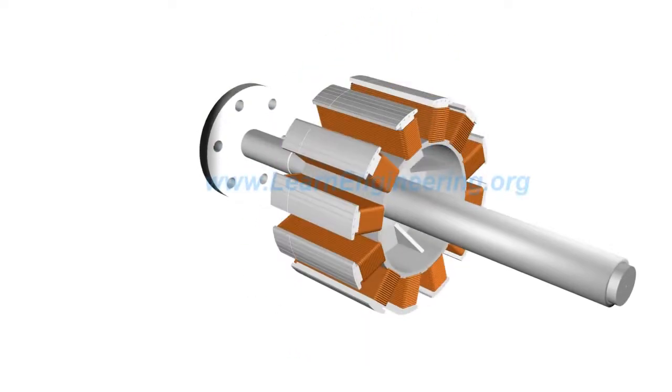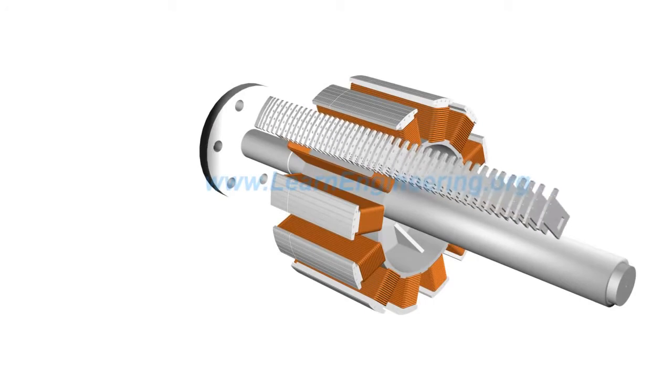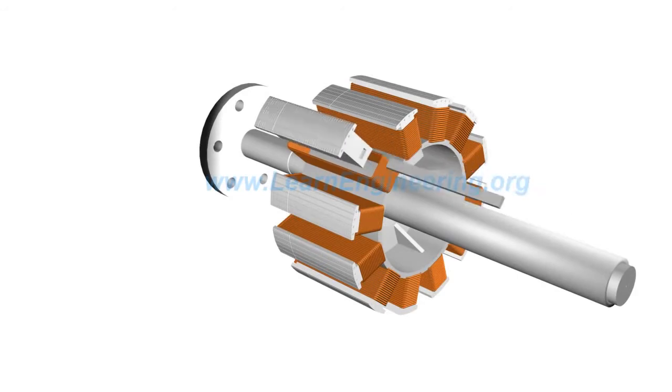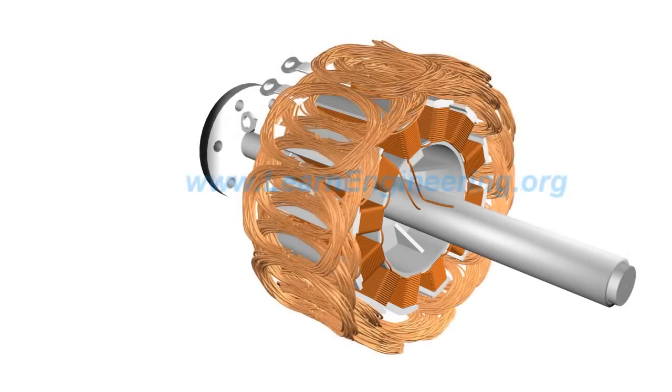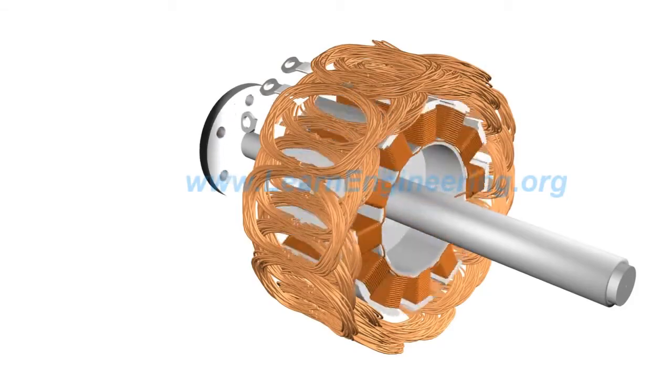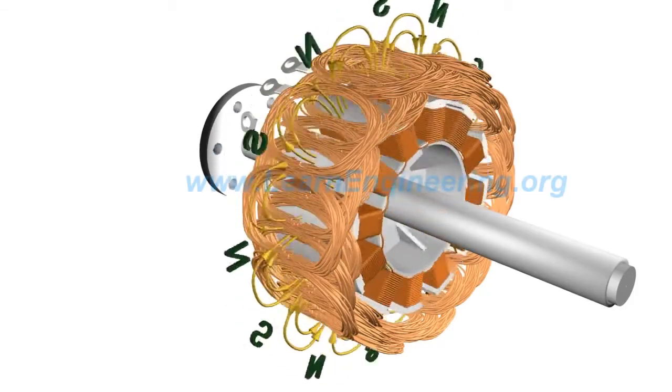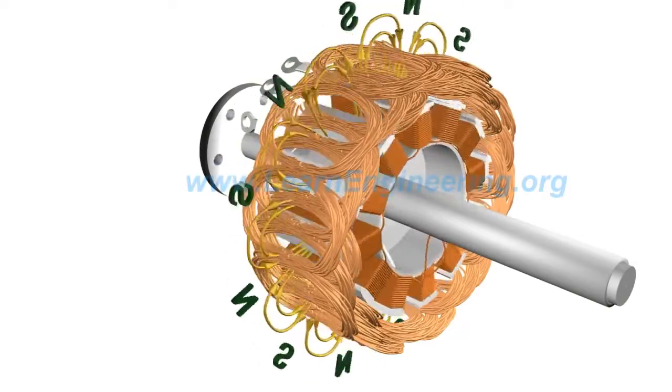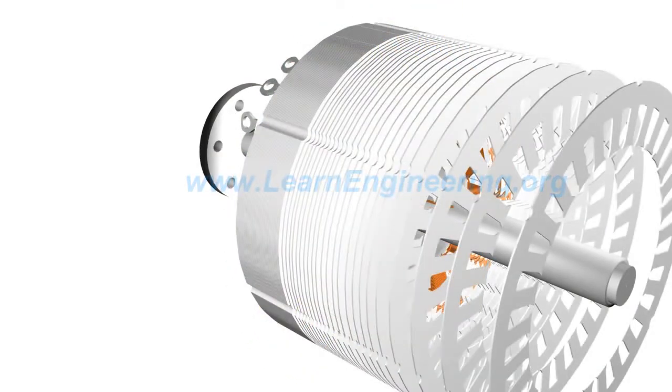Pole core is used to effectively transfer magnetic flux, and it is made with fairly thick steel lamina. Such insulated lamina reduces energy loss due to eddy current formation. Armature winding of a 3-phase 12-pole system is shown here. A stator core is used to enhance magnetic flux transfer.